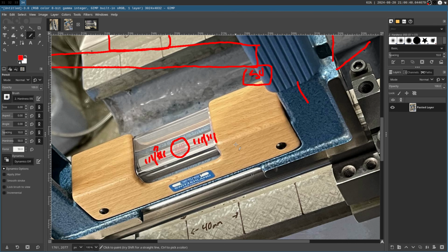My surface plate is level enough that this always reads within a couple divisions. Obviously, the level is most accurate when near the center of the divisions. So when you're calibrating your level, you want your reference surface to be as close to level as possible so that you aren't reading something off the charts here, obviously, right?